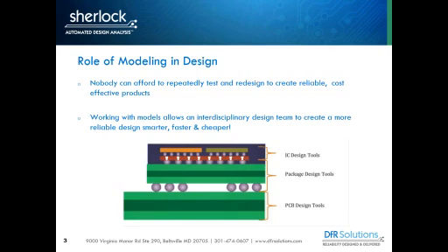If you identify a reliability risk and make the changes in the design and then do some type of simulation to verify that those changes will actually increase the robustness of the product, that's the least expensive technique for generating a robust product. So it allows you to make a much faster time to market because you're decreasing the number of redesigns that you have to do.